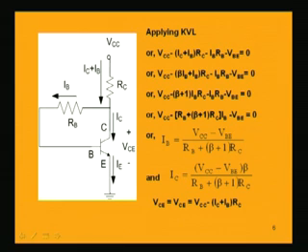If we apply Kirchhoff's voltage law, then from this point, it is of course positive point of the VCC, and it will be VCC minus this drop, which is equal to IC plus IB into RC, minus this drop, which is equal to IB into RB, minus VBE, base to emitter voltage, that is equal to 0, because this point emitter and ground, that is the same point, we are not having any resistance there. So, this is at ground potential, emitter is ground potential.